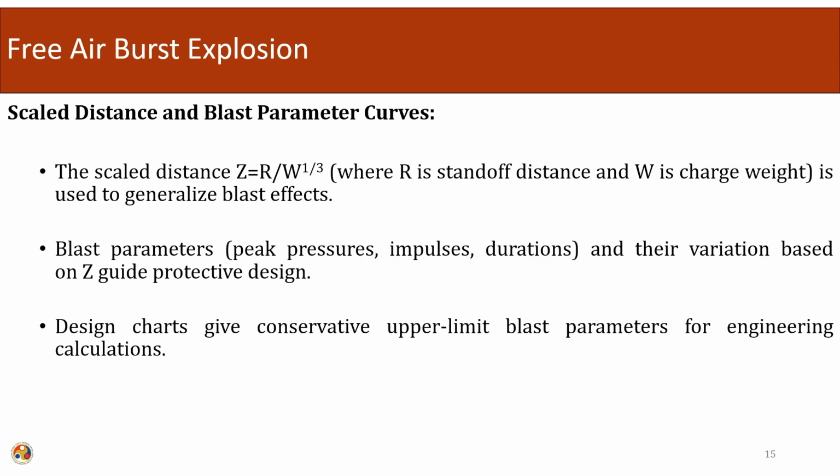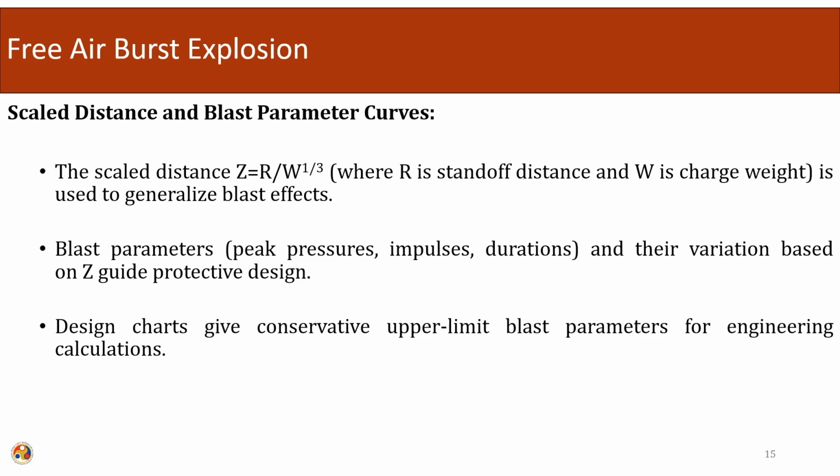Scale distance and the blast parameter curves. Earlier we have seen the TNT equivalency. So, the TNT equivalency was used to establish the effect of the different weights and different types of chemical used for the explosion. The scale distance parameter and blast parameter curve is used to establish the effect of the pressure depending upon the amount of the charge and the distance from the charge.